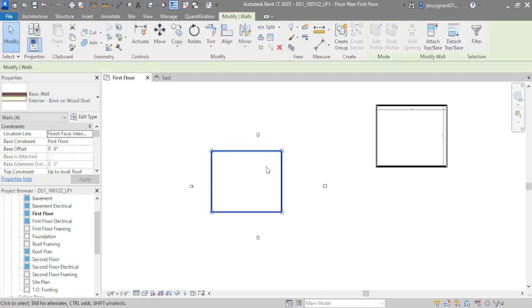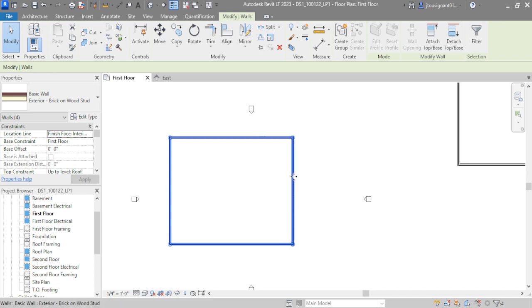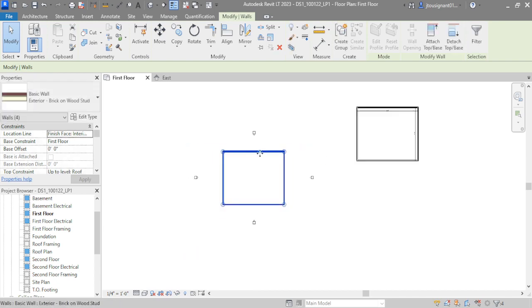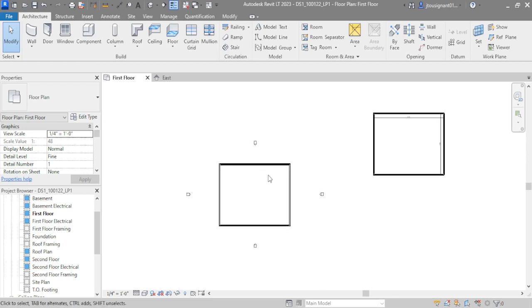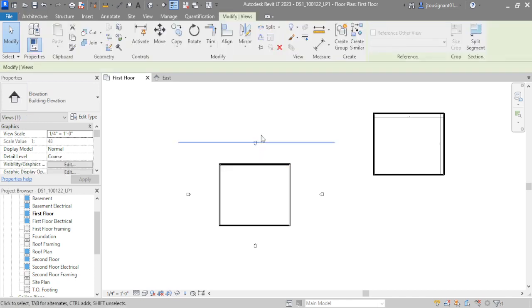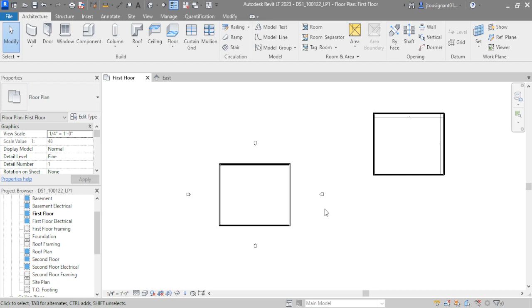Because I've only drawn these four walls, I can confidently just select these items and kind of drag them more into the center of our default drawing space, which again, you don't have to be very driven on making sure it's in the center of. It's just helpful, because then your building will be in front of your elevations, not being cut by them like a section, and you won't have to make as many adjustments later. But that's also avoidable if your building is too big for the original drawing space anyway. So we've got this drawn. That is drawing using the location line.